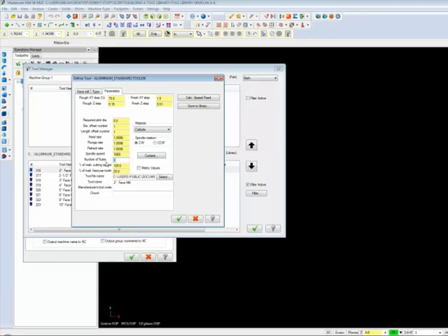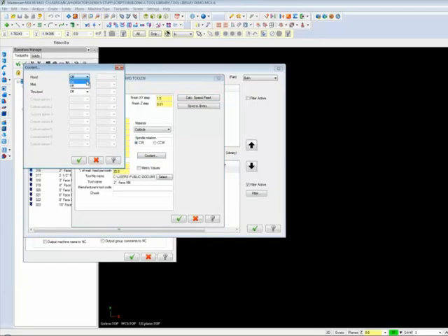The tool manufacturer hasn't supplied us with feeds and speeds, but we can come up with something pretty close and tune it as needed. Since we've entered the insert material as well as the number of inserts, we can click on the Calculate Speed Feed button to get a good starting point for the tool. Click on the Coolant button and turn Flood on.